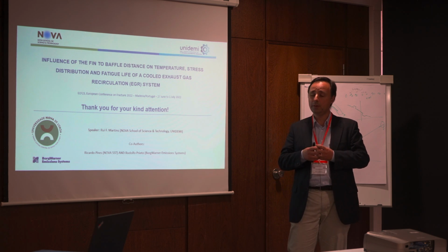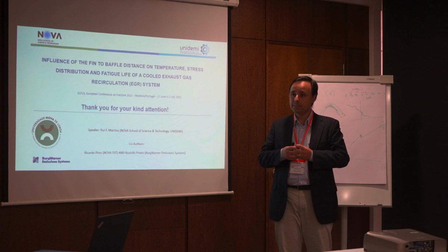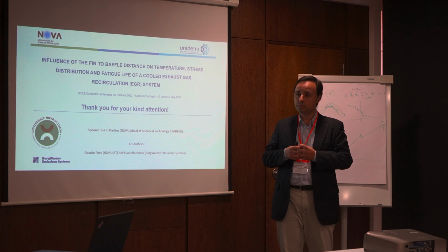Regarding that, you talk about the Coffin-Manson equation. If you consider the properties for the temperature, I don't know what is the temperature in your case, but are you using the room temperature properties or high temperature fatigue properties?